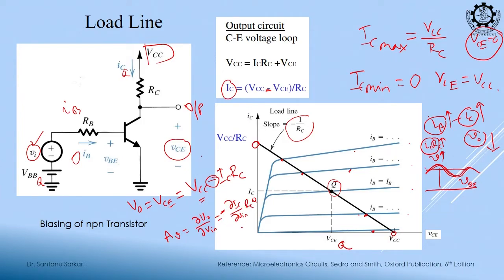What is del I by del V? Transconductance. So, this is my transconductance if I term it as GM. So, this is my gain. This gain is large signal or small signal? This is small signal gain. This AC signal is small signal, no? And you see this DC term, if you do derivative this is 0. So, this is only containing the AC signal.